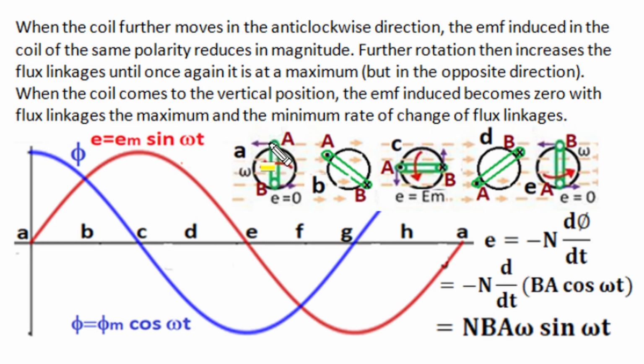Anti-clockwise rotation of the rectangular loop from position A to position C results in reduction in flux linkages as the cosine of the angle between the B vector and the area vector, and as per the rate of change of this cosine function, the induced EMF becomes a sine function of the angle between the B vector and the area vector. As time progresses from A position to C position, as omega t increases, as shown in this red wave, the induced EMF increases and becomes maximum at position C when the coil plane is aligned with the magnetic field force lines.